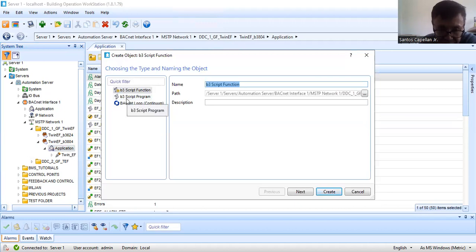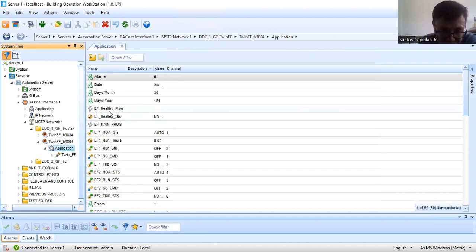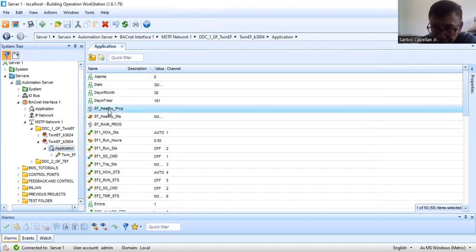Now you just select this B3 script program. Then give the program an appropriate name. It should be descriptive of the purpose of the program. Like this one, EF Healthy Prog. It means this is the program that will give me an alarm or a status if my exhaust fan system is healthy or not. I already explained that to you.